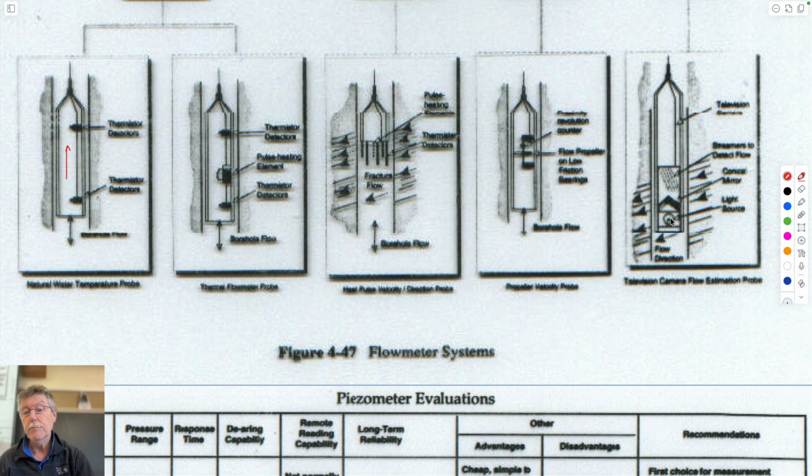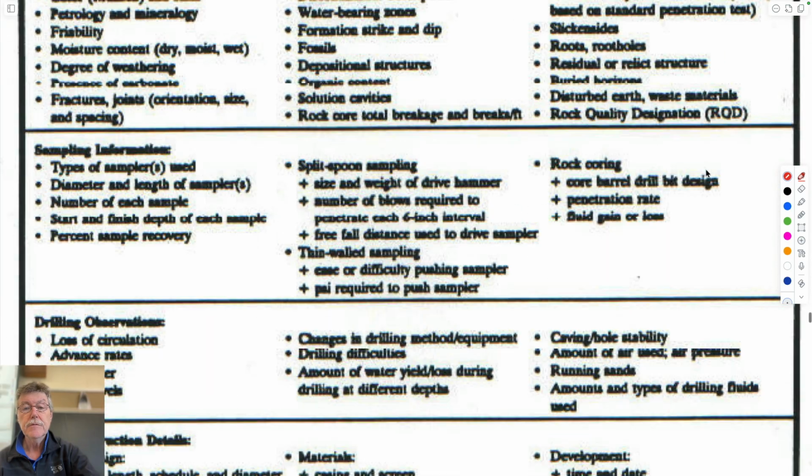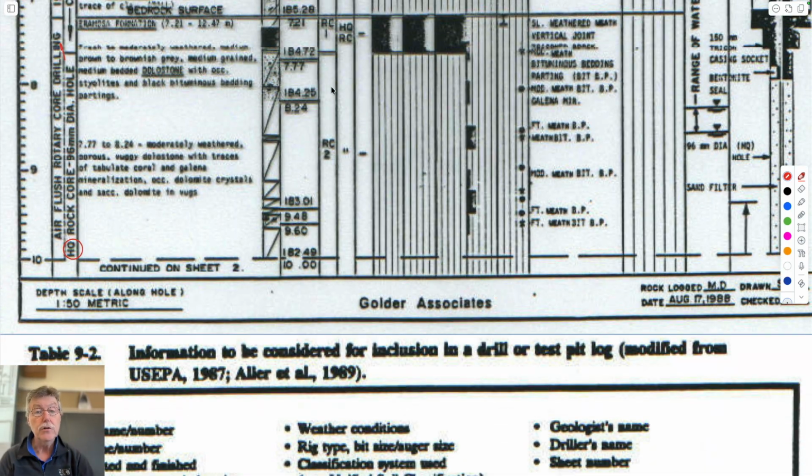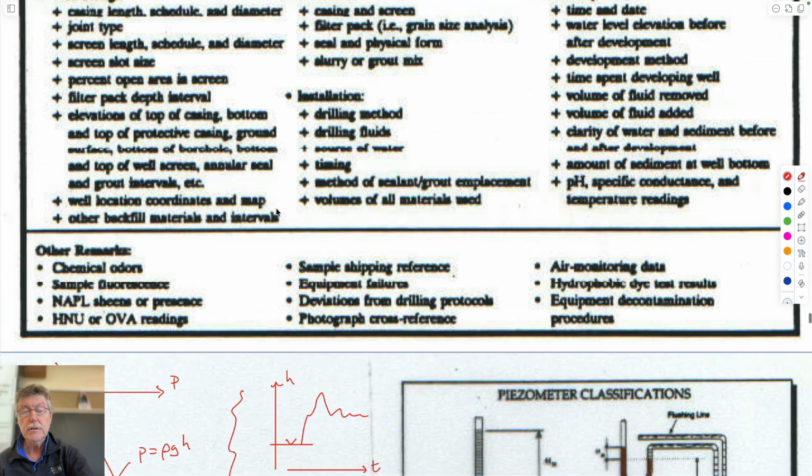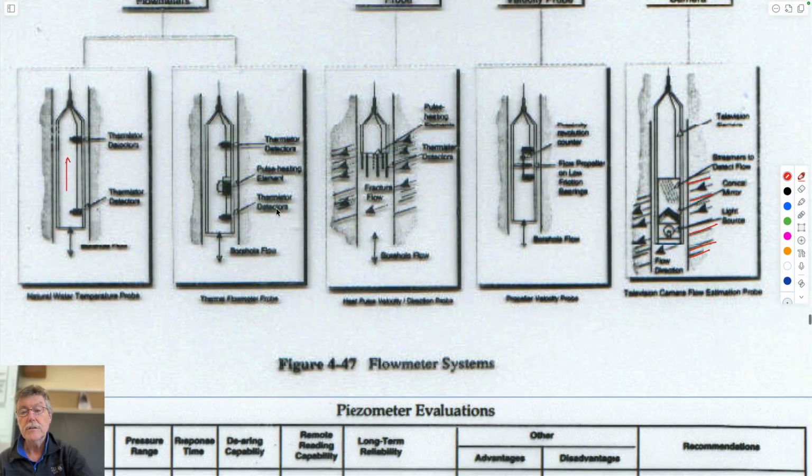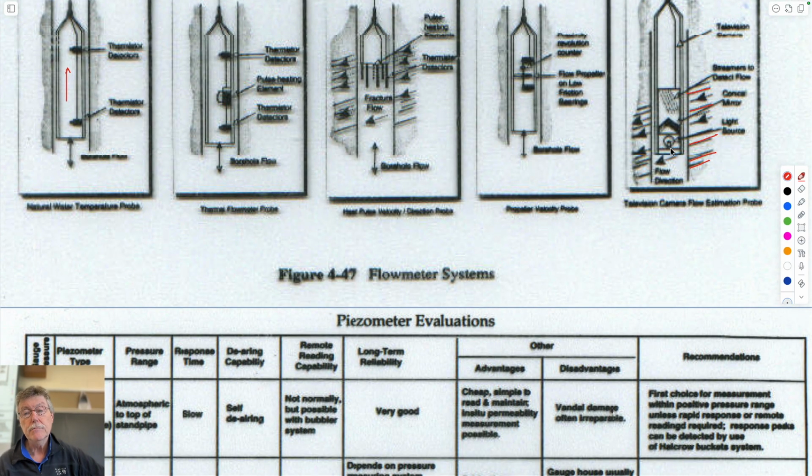Maybe more common today, you get borehole cameras. You drop a camera down the borehole, you run it along the full length, and you film all the way along. And a couple of things you can do. Really the main objective is to look at the structure on the borehole wall. You can pick out the location of fractures. Of course, you'll get fractures in the drill core as well. And so if you do it in a hole that's already been cored, you can ground truth it for parts of the borehole which perhaps wasn't sampled.